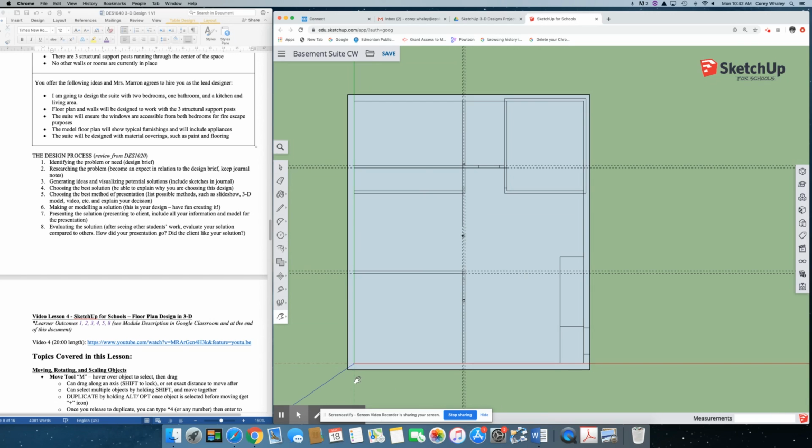So now, just to clean up the area so it's a little bit easier to see everything that's going on, I'm going to start to erase some of the guidelines and things that we no longer need. So grab the eraser tool and you can just start getting rid of these guidelines, which we no longer need. You just basically hover over it and get rid of all of those lines. Okay, and actually another thing, these little extra pieces here, we're not going to need those anymore either.